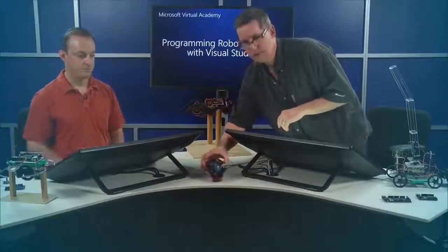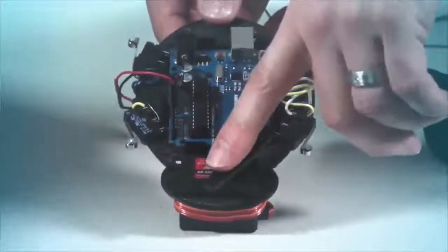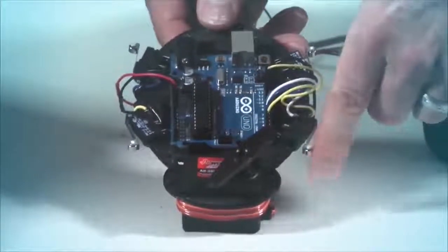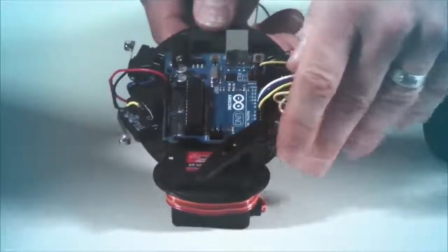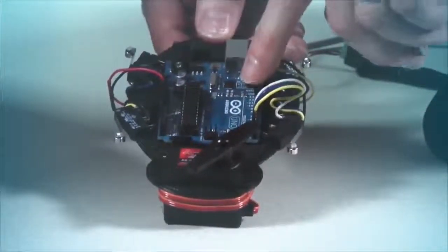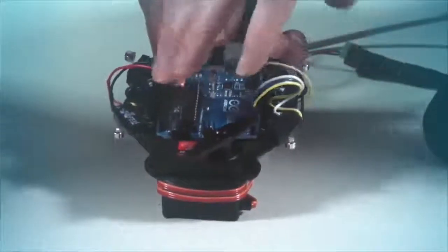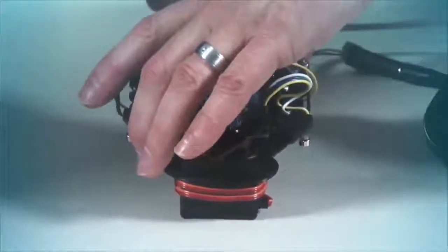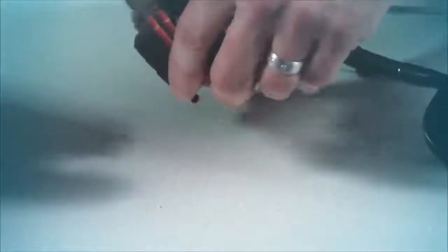So check that out. All right, so Paul, all I need to do here, so we got this new little guy here, and he's got the servo in front. That servo's going to run until we touch one of these switches. That should momentarily stop that servo as we touch each one of these. We're wired up to 4 of the digital pins, grounded, and we have a wire for the servo and some power. So I am going to plug in the board to my PC so that we can upload that program.